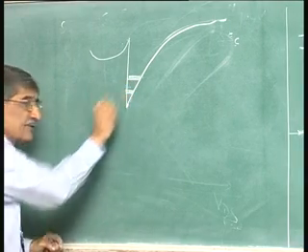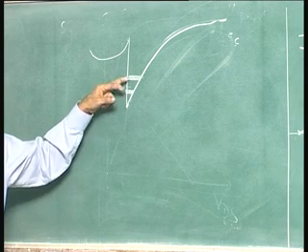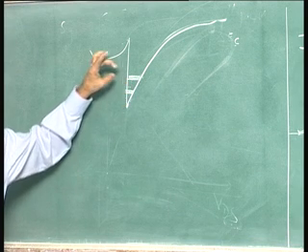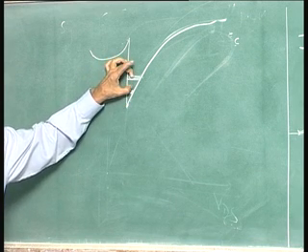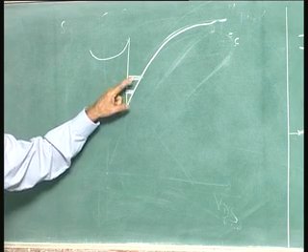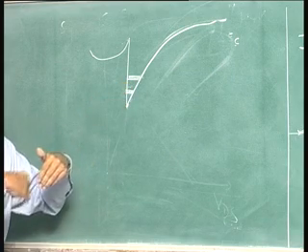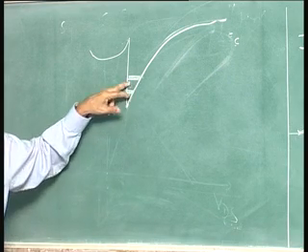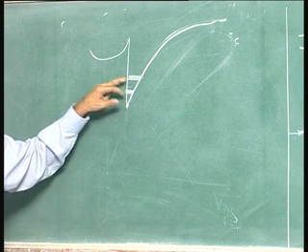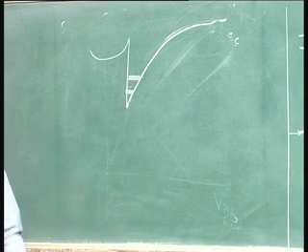It will fill up these levels first, it will go to these levels afterwards. More and more will get filled up here as you go to more and more gate voltage. Okay. And in these levels the electron mobility is slightly smaller than this. Go to the higher energy, you have lower momentum. In fact, you can see those curves, you go up in the momentum curve, the effective mass slightly falls here. So, because of the fall in the mobility, the transconductance is not as high.